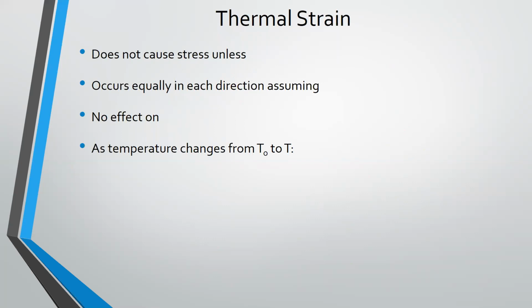In what situation will there be stresses associated with that? What if it is inside of something? Yes, when it's constricted. So if I have a rigid cylinder around it, stopping it from being able to expand, now it's going to develop stresses because the temperature makes it want to expand, but it's not allowed to. And so that restriction causes compressive stresses in there.